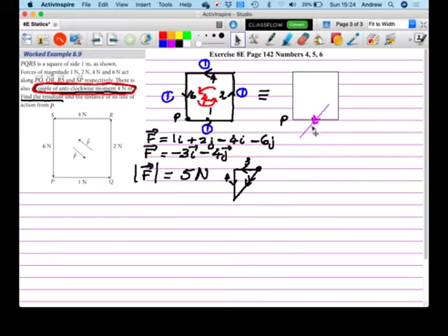If I put it in the wrong place, the distance comes out as negative, and therefore you have to write a written explanation saying, oh, D came out as negative, which meant my line of action, let's say it was below P, isn't below P, it's parallel and above P. So I have absolutely no idea where this force is. It could be over here, it could be over there, no idea.